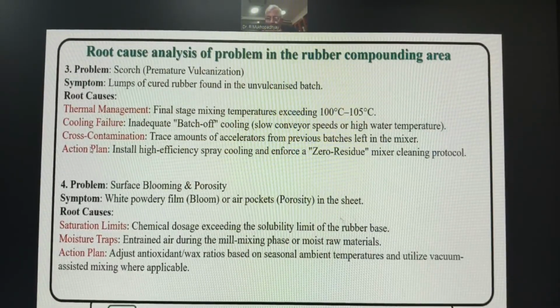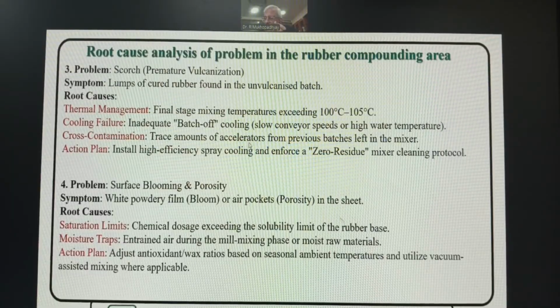Cross contamination: some amount of accelerator from the previous batches is left, and the fix is to install a high-efficiency spray cleaning system with a zero-residue mixer cleaning protocol.